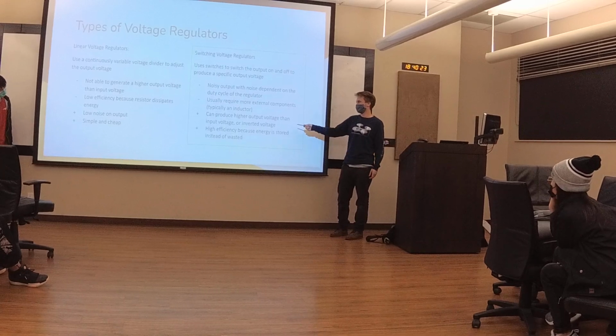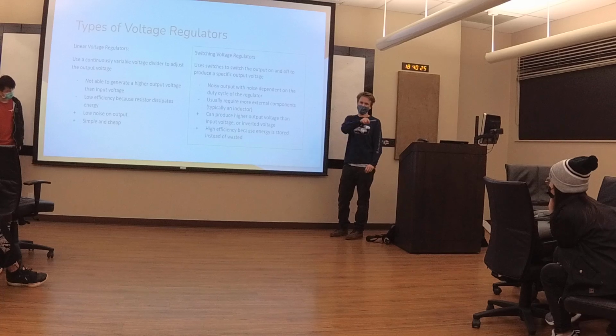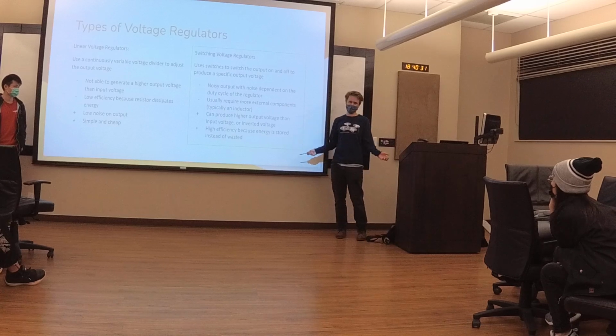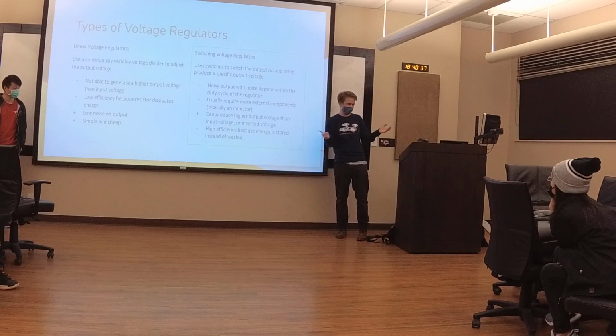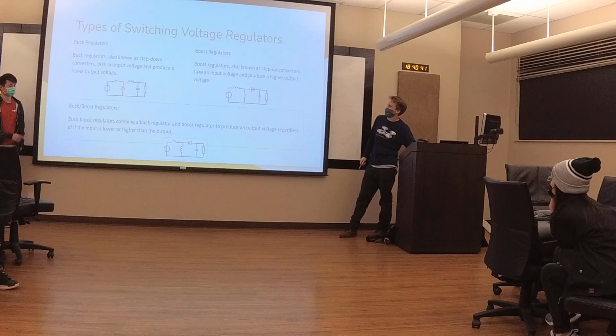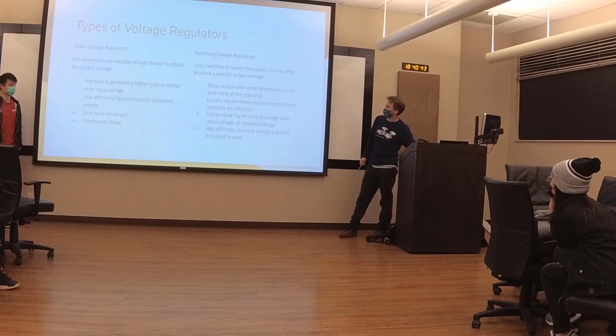That being said, they can produce a higher output voltage than input voltage, so they can raise it, which is something you can't do when you're just dropping potential across a resistor. The other thing is they're really high efficiency because they don't use a resistor, and the inductor stores energy instead of dissipating it, which means they don't waste energy. To confirm, in your sample applications for voltage regulators, a common thing is to see at least one inductor and a lot of decoupling caps. Yes.